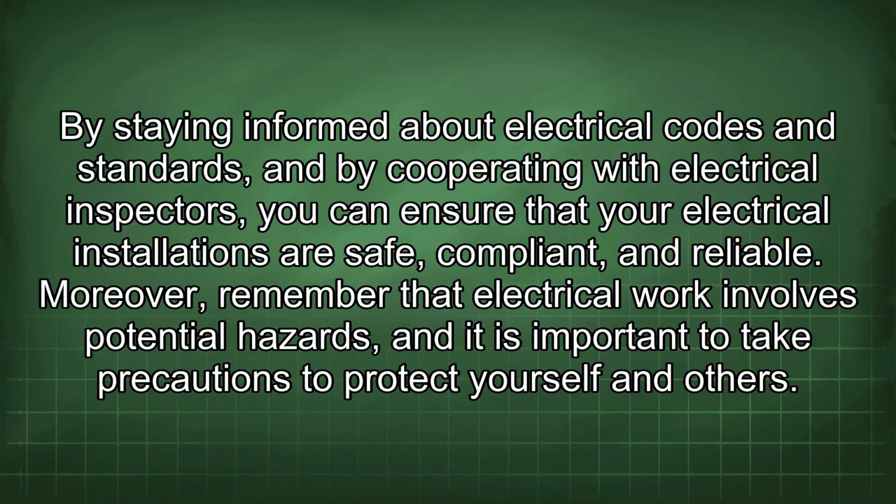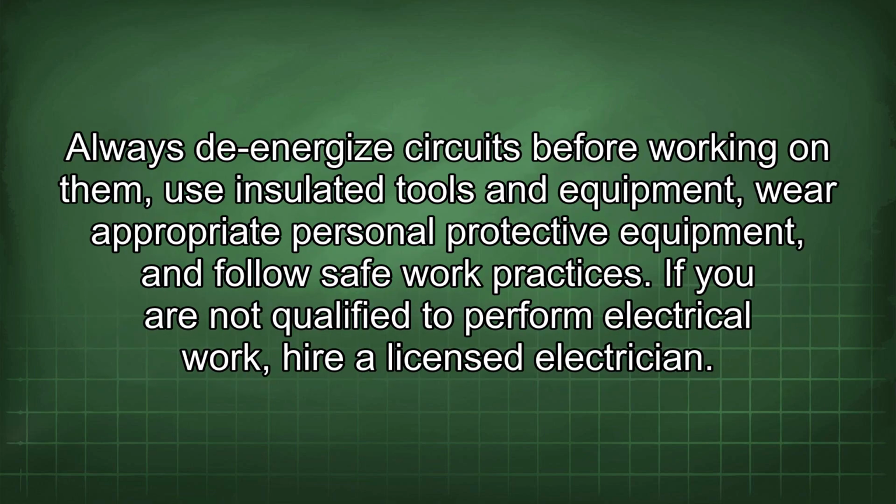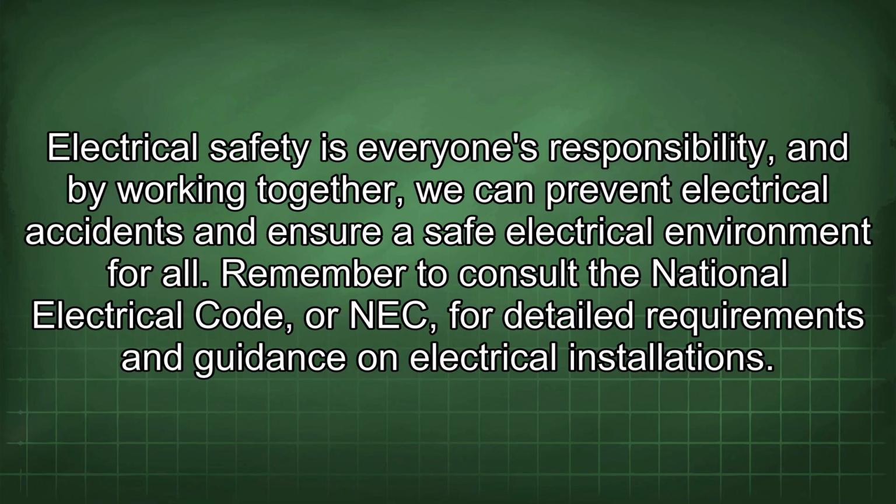Moreover, remember that electrical work involves potential hazards, and it is important to take precautions to protect yourself and others. Always de-energize circuits before working on them, use insulated tools and equipment, wear appropriate personal protective equipment, and follow safe work practices. If you are not qualified to perform electrical work, hire a licensed electrician. Electrical safety is everyone's responsibility, and by working together, we can prevent electrical accidents and ensure a safe electrical environment for all.